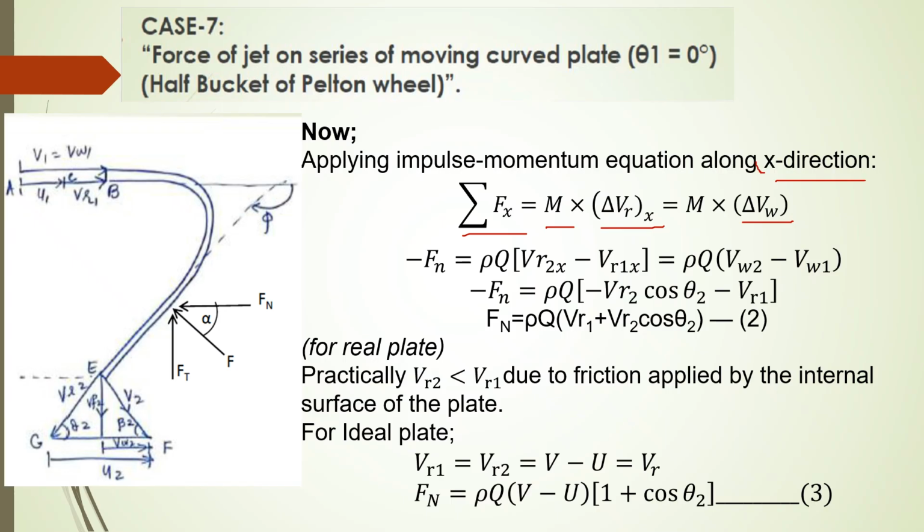So if we are doing our calculation for Fn, the x directional component of the resultant force, the force of the jet, we need the x directional forces. With respect to V2 these will be the whirl velocities, and with respect to the relative velocity, it should be delta VR and its x component.